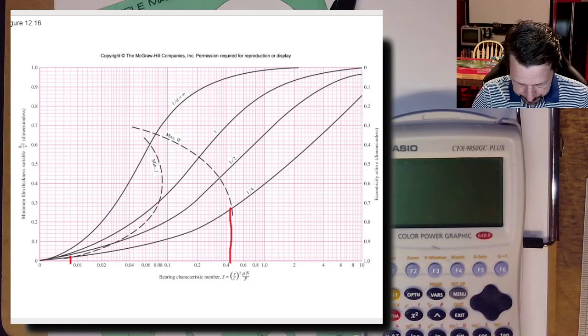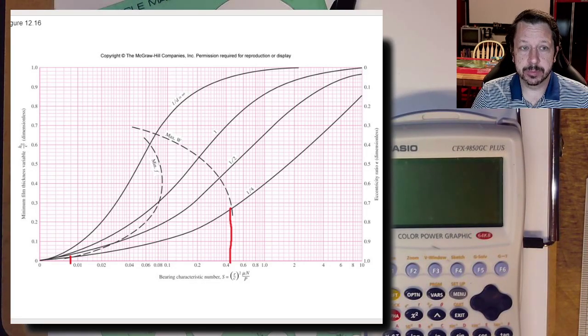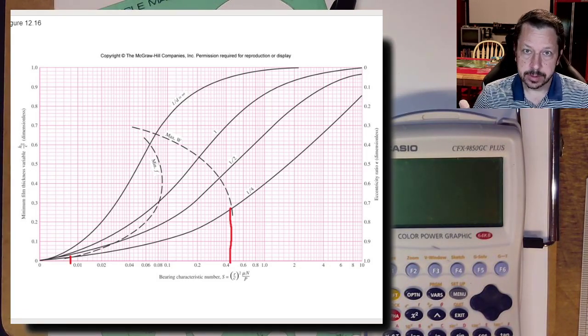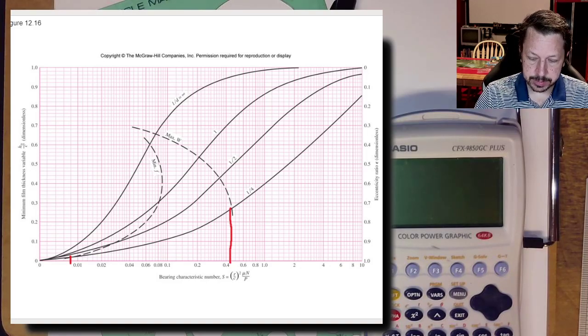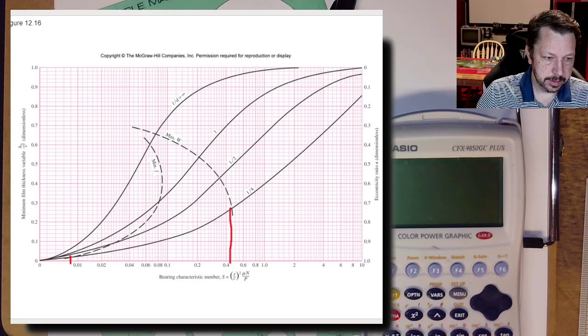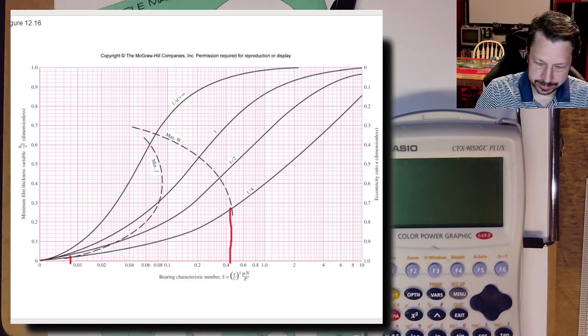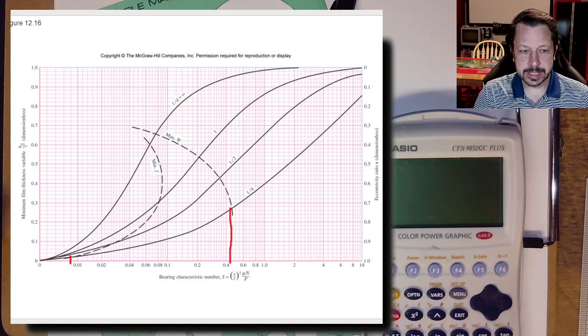All right. Now, once we know that, we can actually figure out the size for our bushing. So the bushing diameter, we'll call that uppercase D, is just going to equal the journal diameter plus 2 of these clearances, 1 on each side. So there is the size. Oh, hold on. We multiplied. There we go. There is the size of our bushing. So it's a 2-inch. Remember, that was the diameter of the journal. So 2 inches plus 2 clearances.